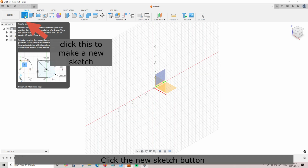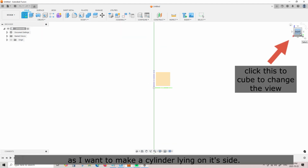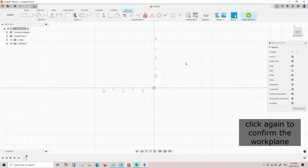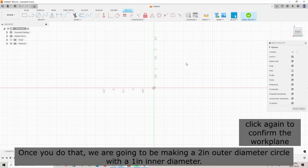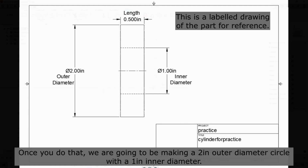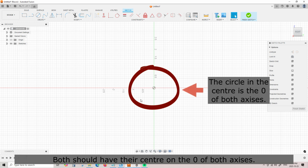Click the New Sketch button and move this cube in the corner to be viewing the right, as I want to make a cylinder lying on its side. Once you do that, we are going to be making a 2-inch outer diameter circle with a 1-inch inner diameter. Both should have their center on the 0 of both axes.